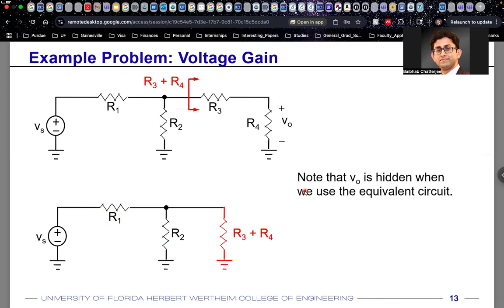All right. So first of all, how do we analyze this circuit? Generally, in a voltage division or a current division analysis, you start from the end and then work your way backwards toward the source. Eventually what you want to know is the equivalent resistance connected in this network, and you want to represent your output voltage to input voltage ratio as a function of all those resistances.